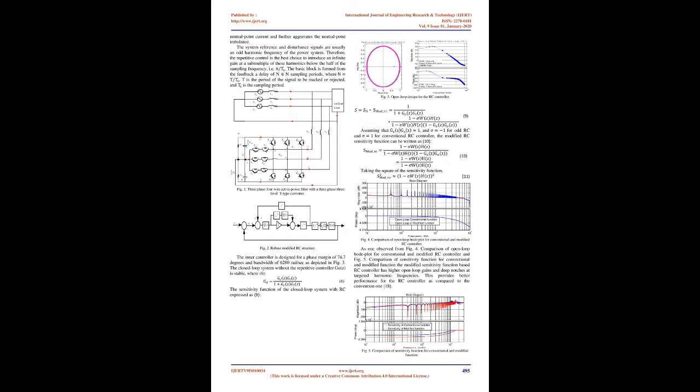The power switch TX1 is turned on to generate a positive AC side voltage, Vx0, which is equal to VDC/2. This effect reduces the compensation phase current ICx as the boost inductor voltage is negative, L dICx/dt = VSx - Vx0. If the compensation current ICx needs to be increased, TX2 is switched on. As a result of this, the boost inductor voltage is positive, L dICx/dt = VSx - Vx0, and the AC side voltage Vx0 is changed to -VDC/2.